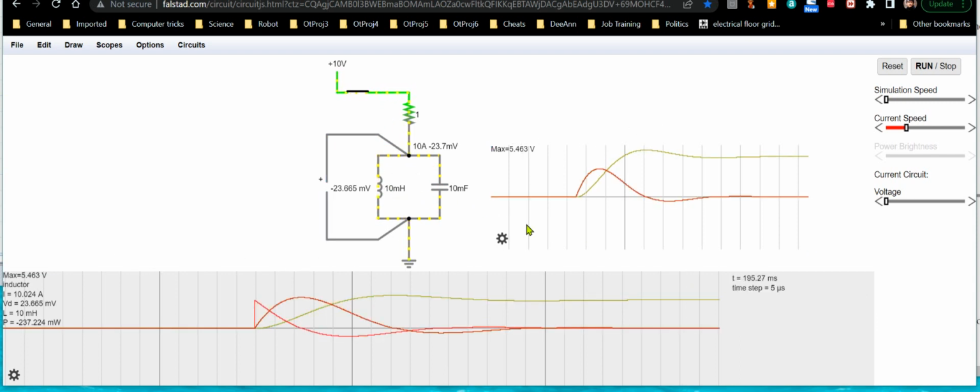A capacitor and an inductor in parallel is a tank circuit. But it has a natural tendency to oscillate, even though it does act like a filter too. If you get into the rest of electronics, this is what you call the condition of maximum impedance. With ideal components, it'll be infinite impedance if you had a frequency flowing through this at the natural resonant frequency of these two components, which mathematically is 1 over 2 pi radical LC.